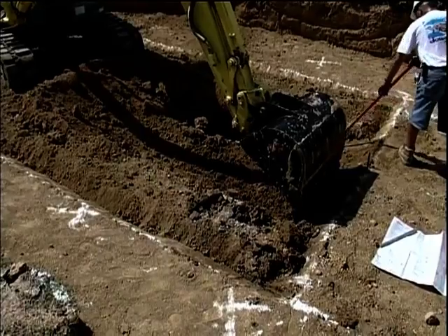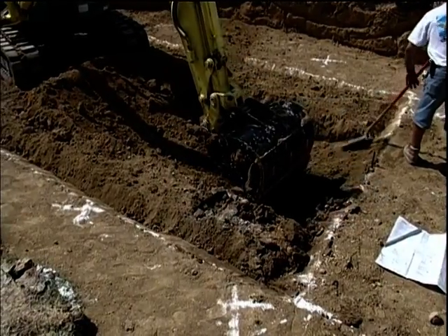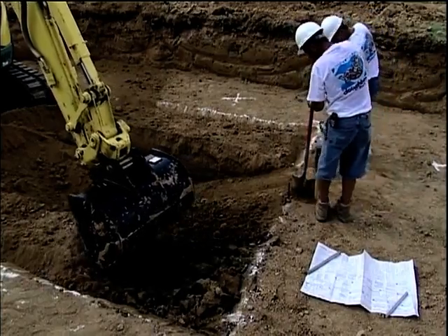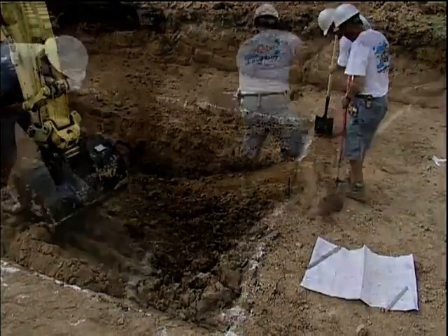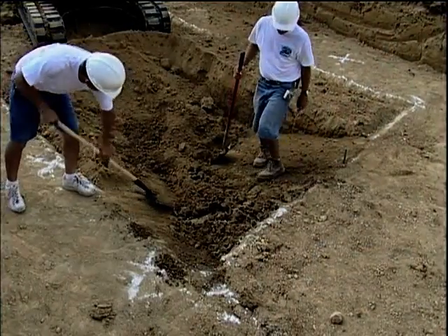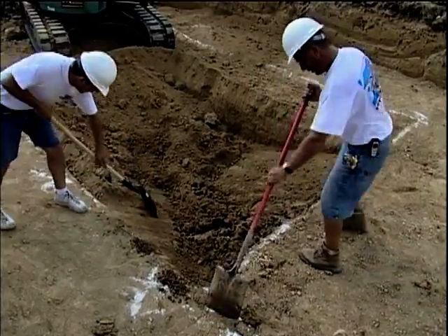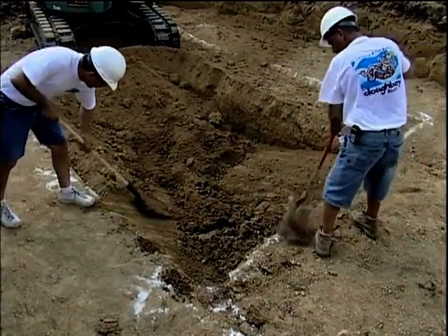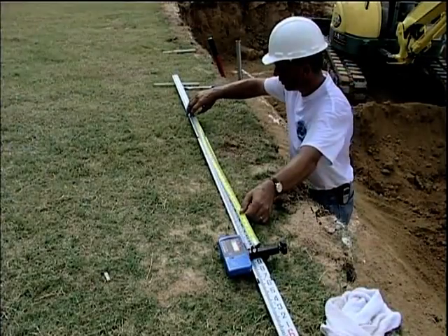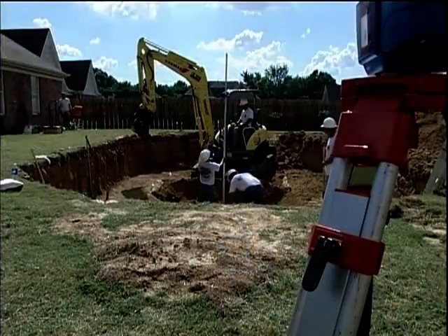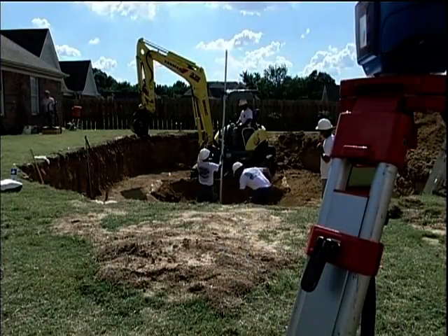To begin the deep swim area, have the excavator start sloping down to the desired depth. For the sides, have the excavator carefully slope them toward the center. Using the flat shovels, contour the side slopes to roughly a 30-degree angle, working down toward the deep end. Readjust your transit to add the final desired depth. Contour the circular end down to the desired depth as well.